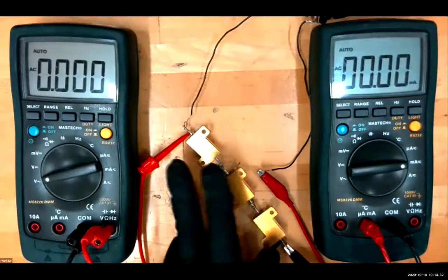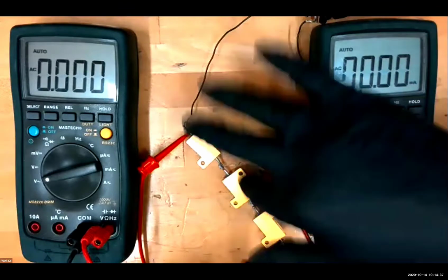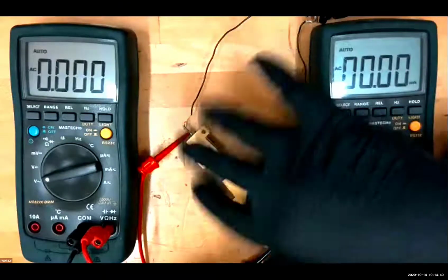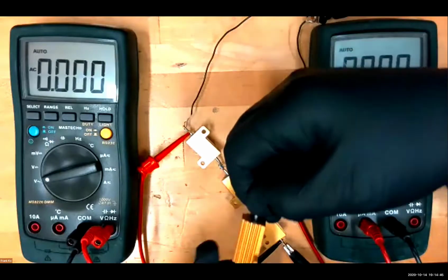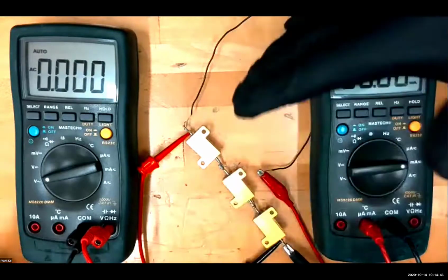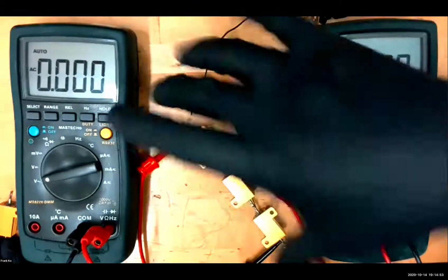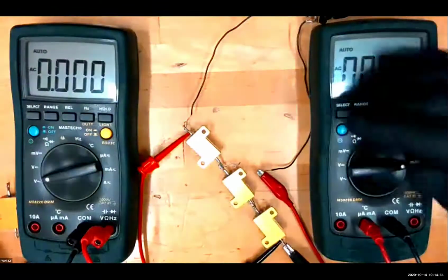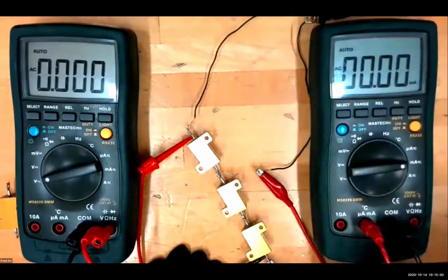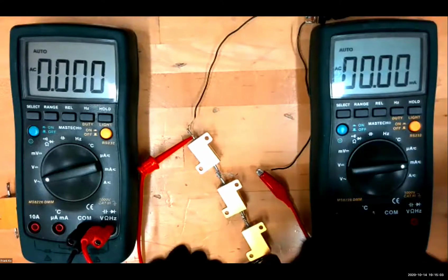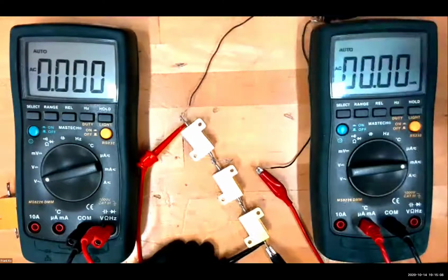But truth be told, we don't want these things to get so hot, especially the singular one. If I have three, they're going to dissipate heat, they're going to get warm, but this singular one will get hot and will burn you if you're not careful. So is everybody understanding the connections necessary to make this lab work? Voltmeter is measuring across. Ammeter has to be part of the current path from the wall wart through the ammeter, back from the ammeter to feed your string of resistors, and then back to the wall wart.